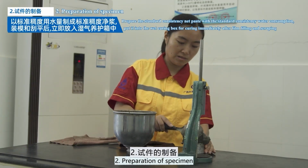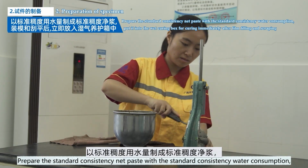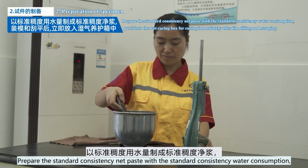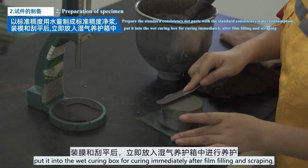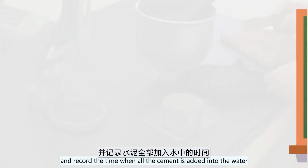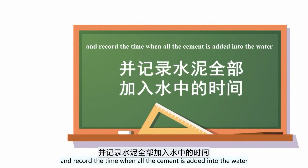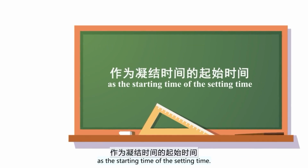2. Preparation of specimen. Prepare the standard consistency neat paste with the standard consistency water consumption. Put it into the moist curing box for curing immediately after filling and scraping the mold, and record the time when all the cement is added into the water as the starting time of the setting time.